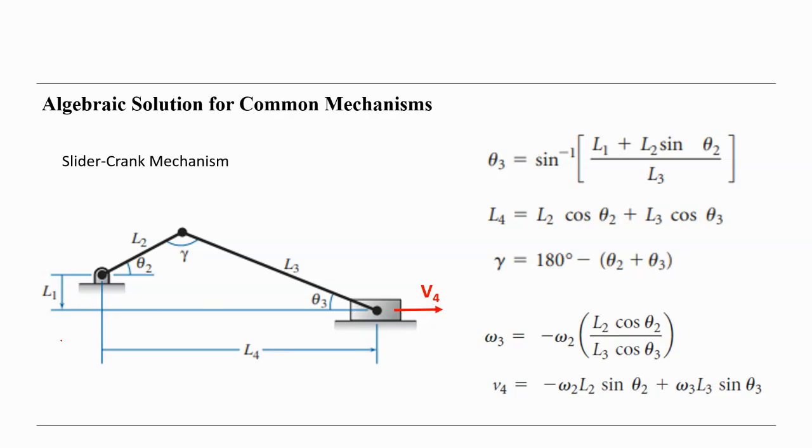This is the general method. If you set L1 to 0, then we achieve the inline slider mechanism. We already discussed how to calculate the geometric parameters like theta 3 here and L4 here. Theta 3 and L4 are very important to calculate.